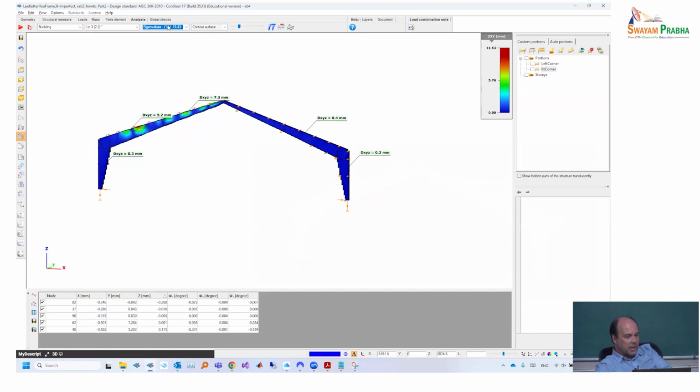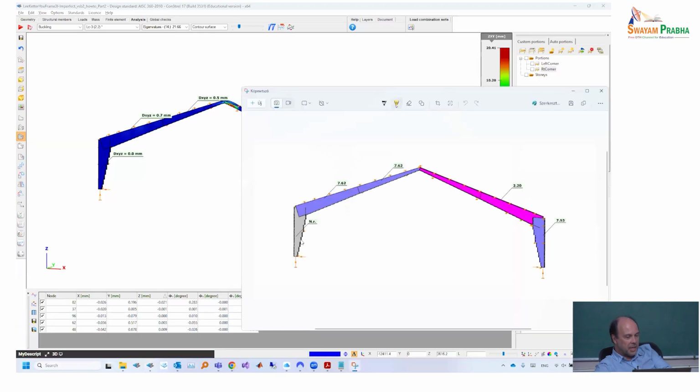And now probably it seems that none of the calculated modes are fine. Therefore, this remains green, and R means not relevant. Not relevant means that none of the calculated modes was giving anything serious and visibly impactful on this column. Now, there might be two things. Don't forget, I said that I'm interested in combinations up to 20.